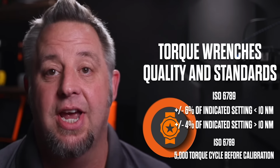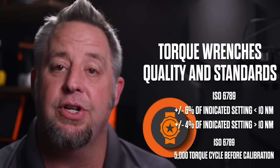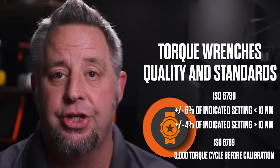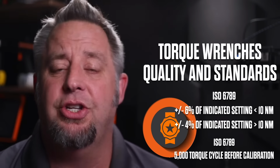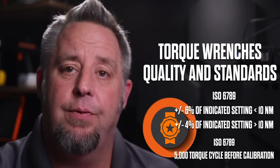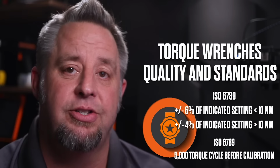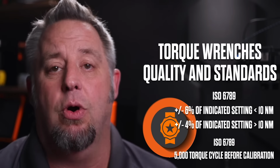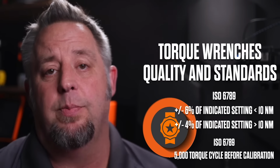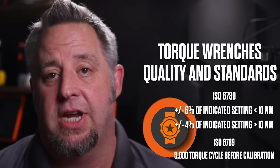And so when I talked about the different standards for torque wrenches, we have two separate accuracy standards. Any value that is below 10 Newton meters is going to be plus or minus 6%. Any value over 10 Newton meters tightens up to be plus or minus 4% of the indicated setting.